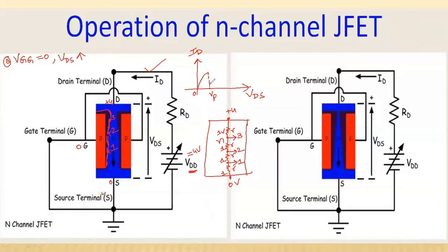Okay, now what is happening at a particular voltage? So this reverse bias voltage will make these two depletion layers increase. Now you can see in this second diagram, let me rub this portion so that it will be more clear for you. So in the first case, say the applied voltage is less compared to the previous case. Say here the applied voltage is 2 volts.